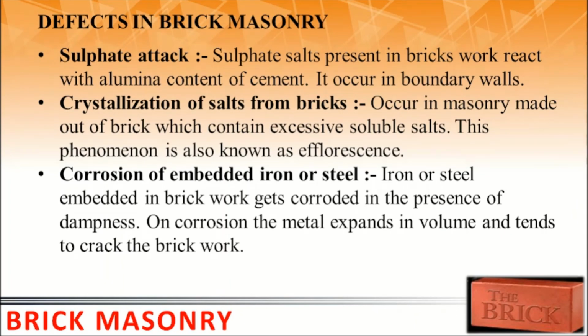Now, I think we have almost covered the characteristics and the nomenclature and the uses of brick, how it is used, where it is used. Normally, if you want to check whether the brick is good or not, do one thing: take a brick, soak it with water for some time. If there are some white patches or black patches, dots on the brick, you will get to know that there is sulfate attack or there are salts on the brick.